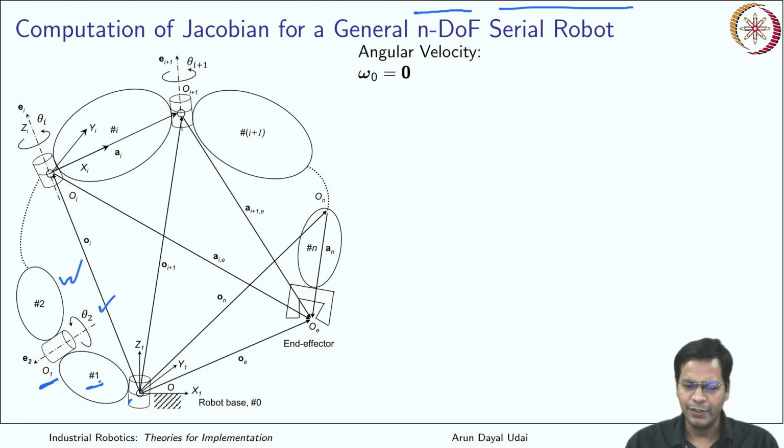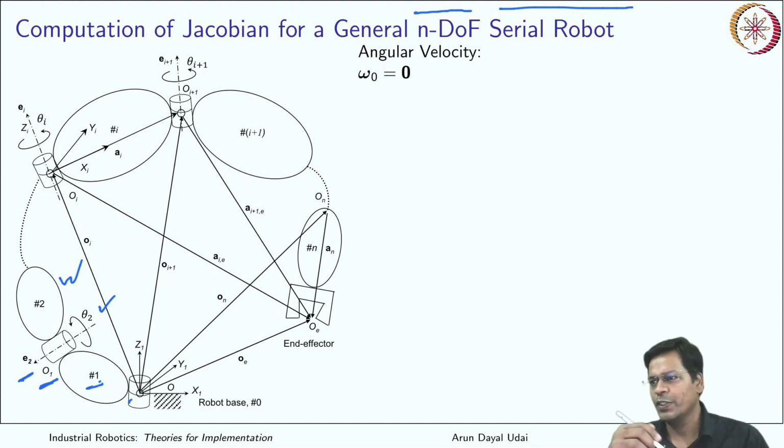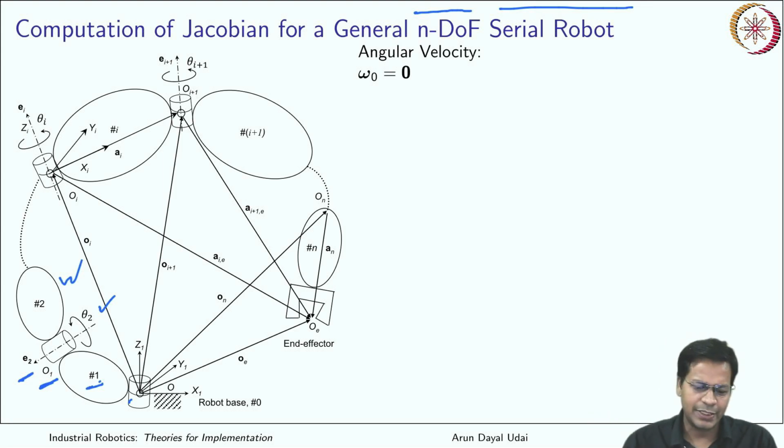Theta 2 is the angle. e_2 is the axis about which this angle is measured. So this is basically your z-axis, which is normally, in case of DH parameters, you know all the z-axes are placed along the axis of rotation or displacement. So exactly these are the z-axes which are there for that local frame. Okay, and then your second link comes like this, and same goes on.